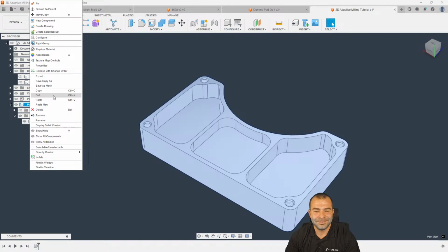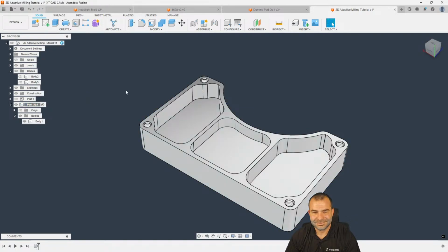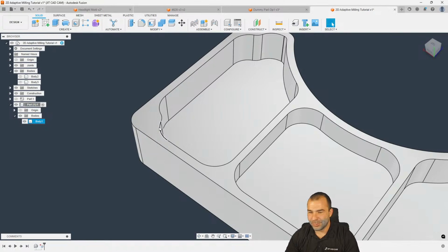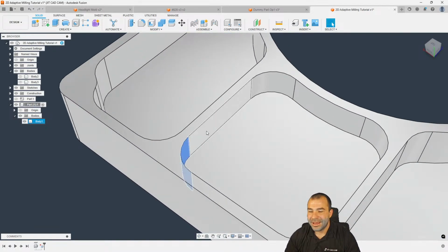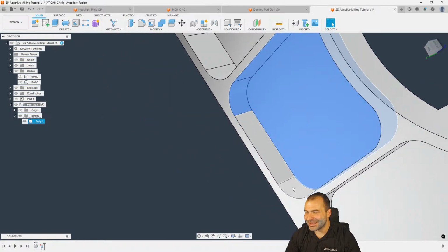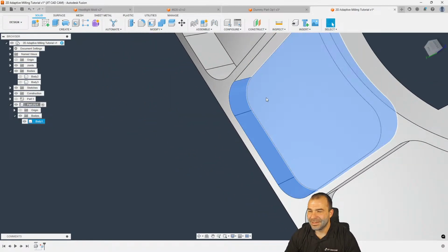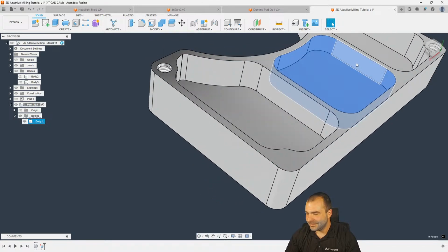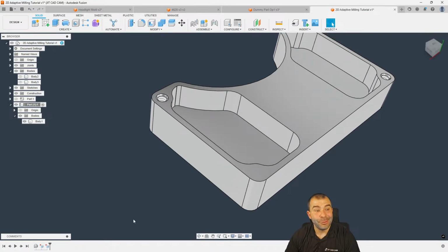Let's activate, isolate, and like he said, we can go through and manipulate this part. So we could remove screw holes in the corners. What should work this time is picking all these walls. If I wanted to remove a pocket, again, I'm doing this by holding my control key, hitting delete. Now it works. Big surprise, right? This is you guys. You put a ticket in, you're like, toolpath doesn't work. I go in and I hit OK, and it works every time.